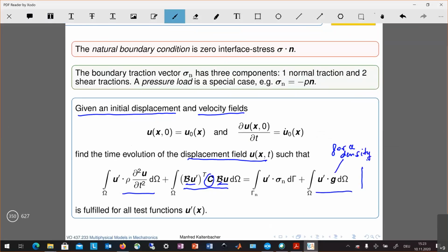given, and we can have here our additional term on the natural boundary gamma n, which we have discussed here in this sense. So in this sense we can put traction boundary condition, which can have, for example, just a normal component, but can also have shear tractions, so which means that the forces per square meter are acting within the tangential plane, so on the surface.